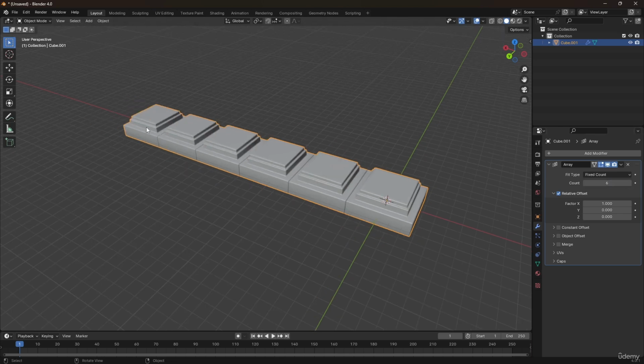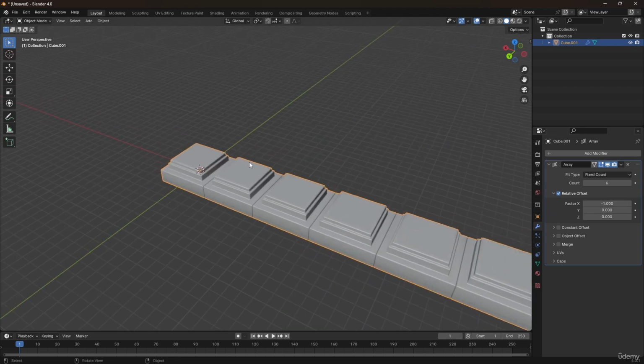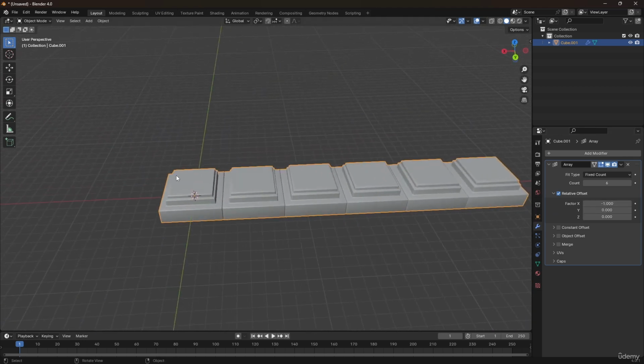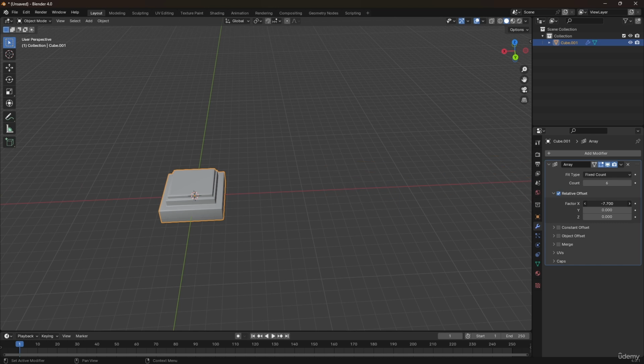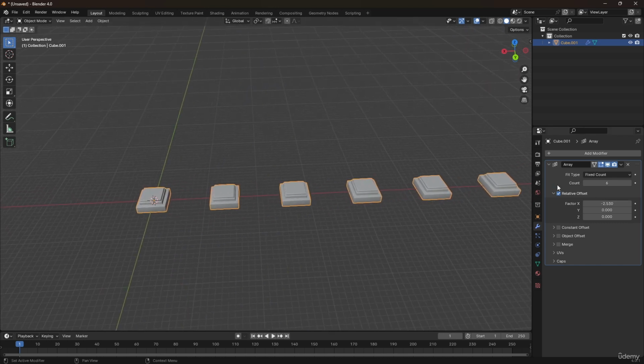And the way of determining which side these bars need to go is this relative offset. So by default, it's going to go on the x-axis. We can do this to -1 axis and like that. And it's just moving 1 unit relative to itself. And if we increase that, we can increase the gap like that. So it's going to give us even spacing very easily and quickly.